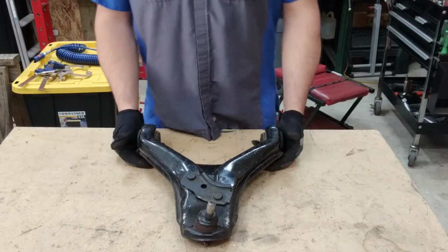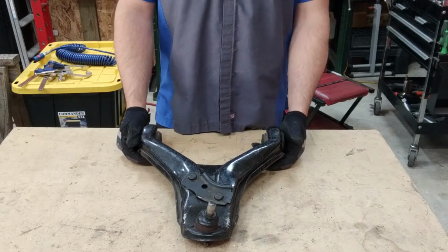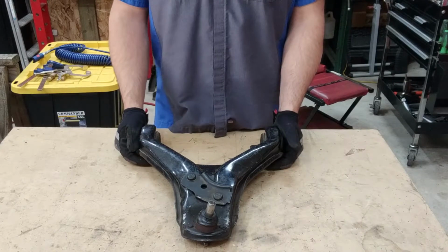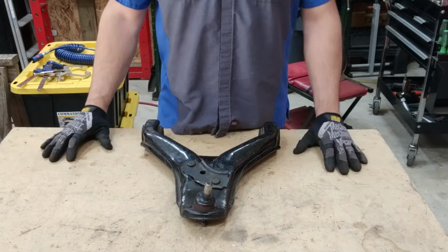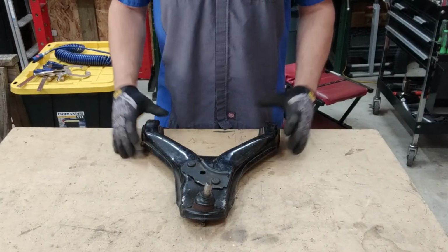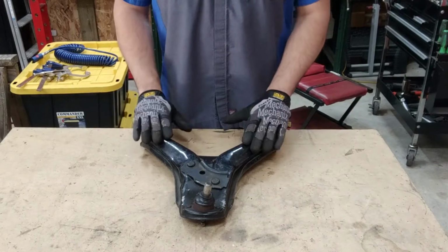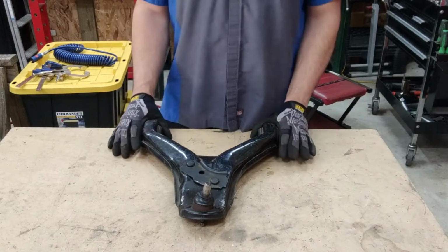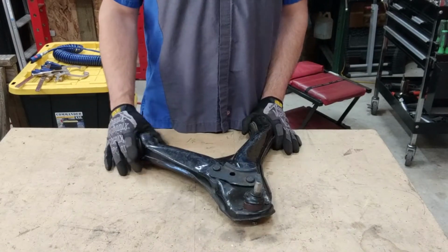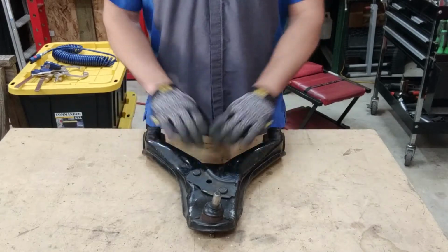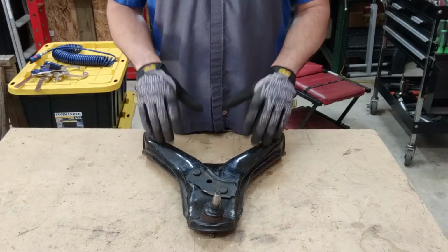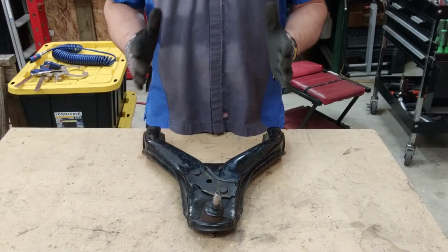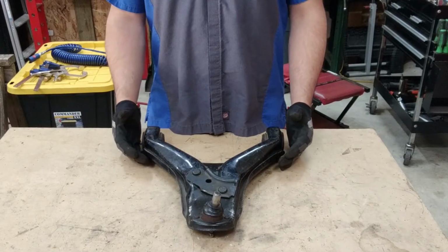Now, as the vehicle is accelerating or slowing down with torque forces through the drive wheels and braking forces, all that transfer is going from the tire to the road, and the road is acting back on the tire itself. So this component has 2 points of contact at the chassis. So that's going to resist the control arm trying to pivot backwards or pivot forwards. So this is a rigid component and does not need any additional links to stabilize it on the chassis in order to help guide that wheel where it's supposed to go.